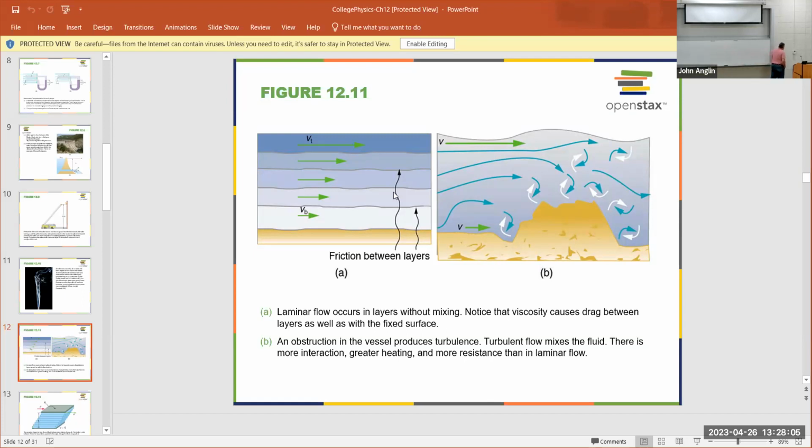You might hear the term viscosity if you watch TV and there's an ad for motor oil all the time, likes to talk about viscosity. This is important in engines. You need oil that lubricates. So you need the oil to reduce the friction between your metal parts. If that viscosity is too high, then those 2 gears will not turn. Those metal parts won't move at all, and that's bad. If the viscosity is too low, then the oil moves through so fast that it doesn't lubricate anything, might as well be air.